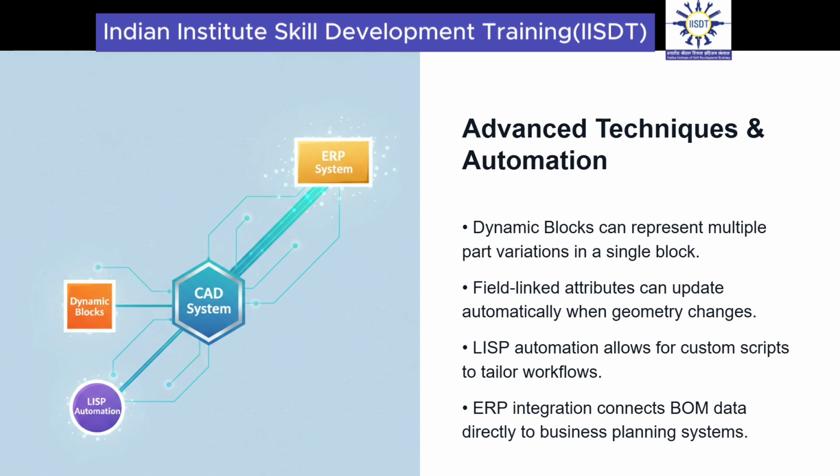For the ultimate level of customization, you can use scripting languages like Lisp. With Lisp, you can write custom programs to automate any repetitive task, create unique data extraction routines, or perform complex validation checks on your blocks and attributes.